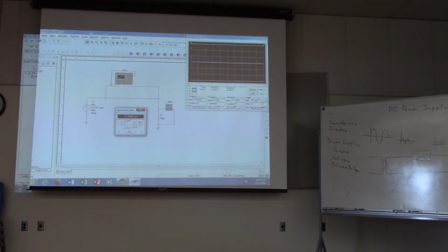Some people say, well, how can I write down in my book what voltage it is? Because half the time it's plus 15 and the other half the time it's minus 18, and it's bouncing around like this. I say the important thing is that it's just about 0, okay? It's a really, really tiny signal that's going up just a little bit, down just a little bit, but really the thing to know is that it's just about 0, very, very close to 0, okay? So just pick a value that you want, one of these that shows up on the meter. Don't worry about it too much. The important thing is that it's close to 0, okay?